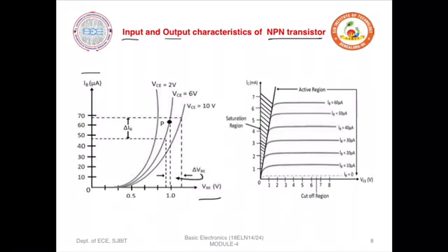In this graph, there is a constant value VC that is being taken, and for increasing values of VBE, the current IB increases. And as this VC voltage, which is kept constant, increases, we can see that there is a reduction in the current carrying capacity.